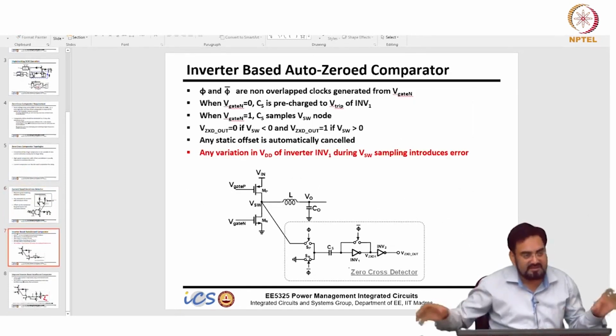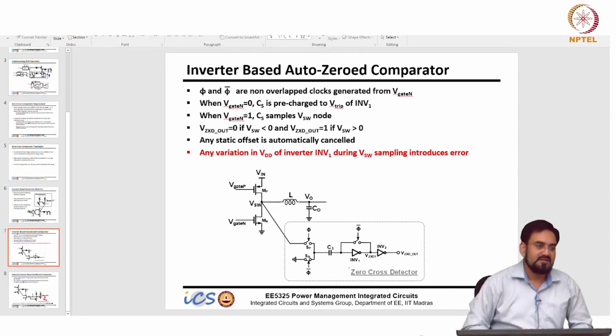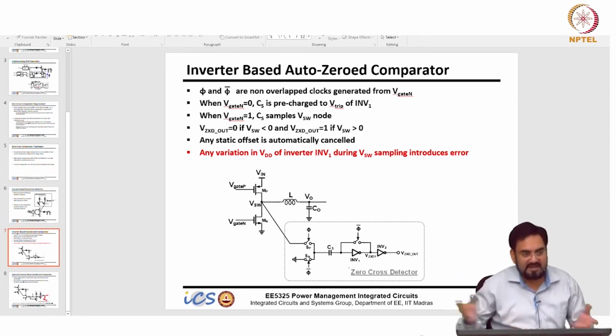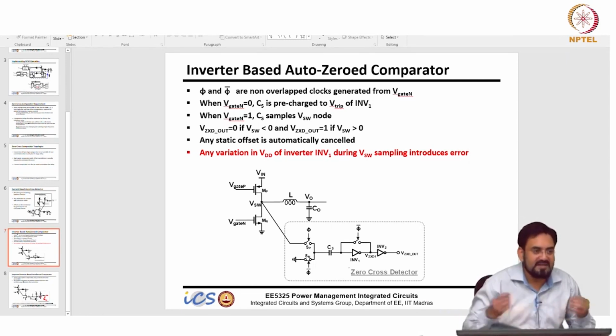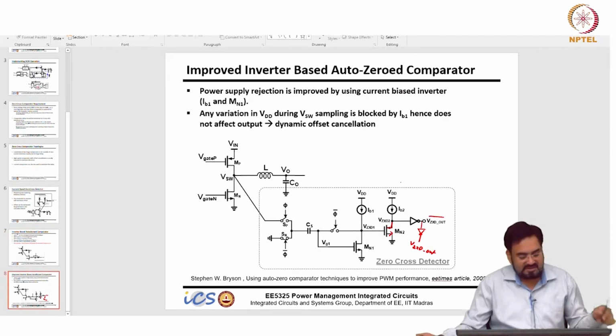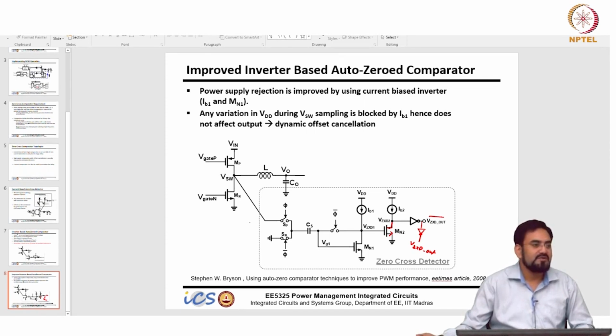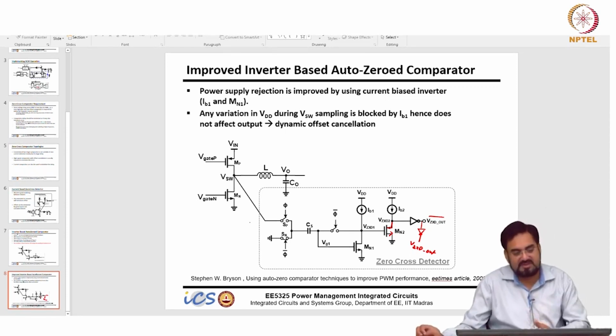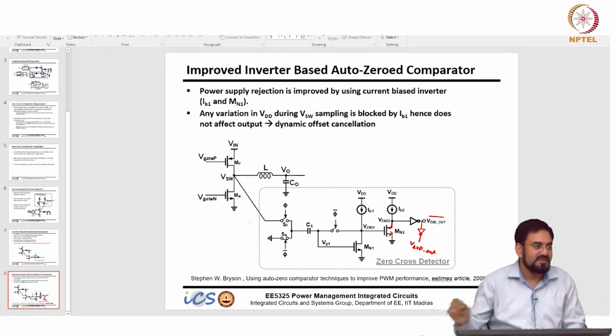Now think about if you are even using a 2-stage comparator, how many transistors you will have, and every transistor will have its parasitic capacitance and increase your delay. So it will minimize your delay. So this is the most important part of your DCM operation, the zero cross detect, and you can use this output to decide when to enter the DCM. Okay, or in fact you can use this to enter into PFM or pulse skip mode also.